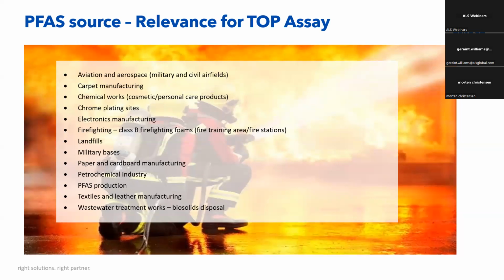There's also sources like primary manufacturing where PTFE is manufactured. Conventional wastewater treatment works have trouble trying to manage PFAS contamination. And we're seeing PFAS up-concentrated in fertilizers, so we've got an issue with biosolids where PFAS has been spread onto land to act as an agricultural improver. And then we've got this issue with up-concentration in cattle and PFAS being impacted as a result of that. But there are other sources as well, where PFAS is used as a mist suppressant for toxic fumes in chrome plating works, for instance. And we're often seeing it in landfill leachate.